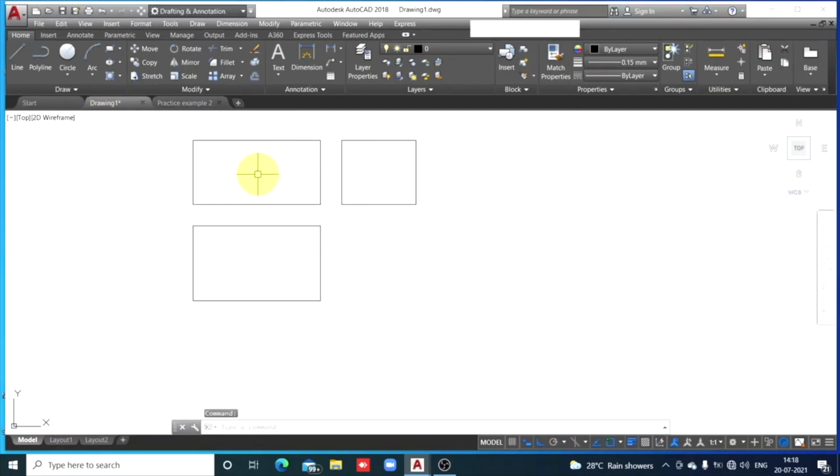So front and back are inseparable in front view. You must know this, that this is right side of the object, this is left side, top and bottom. In the top view, top and bottom are inseparable, but this is right end, this is left end, it is a front end and back end. So front end and back end, or front side and back side, are similar. So here you are going to draw horizontal axis of symmetry, dividing this rectangle in two parts, two identical parts, front side and back side. So let's draw that axis of symmetry.